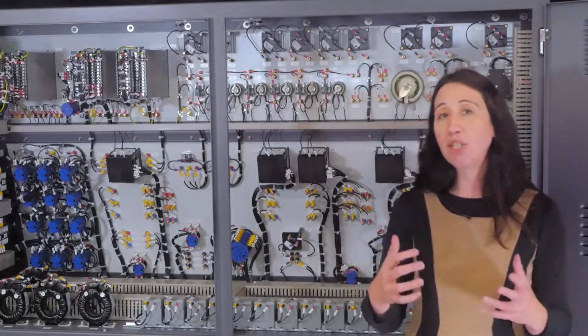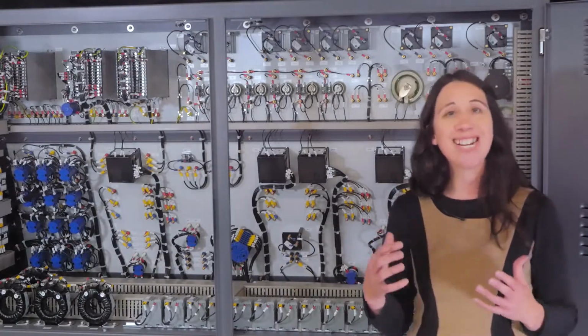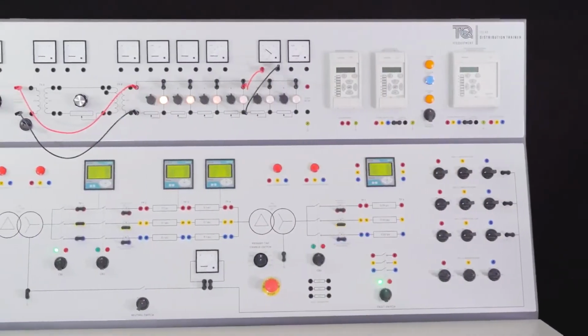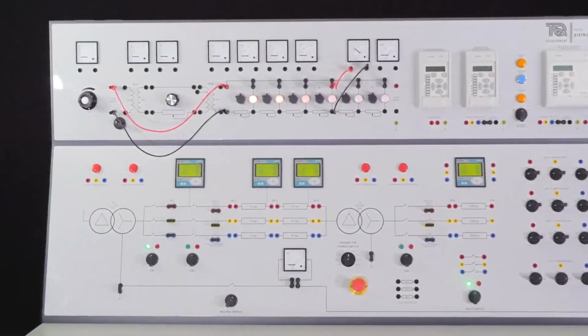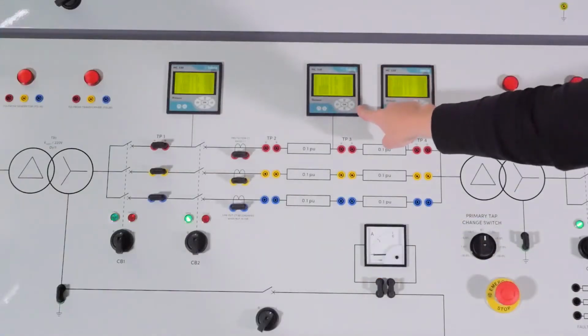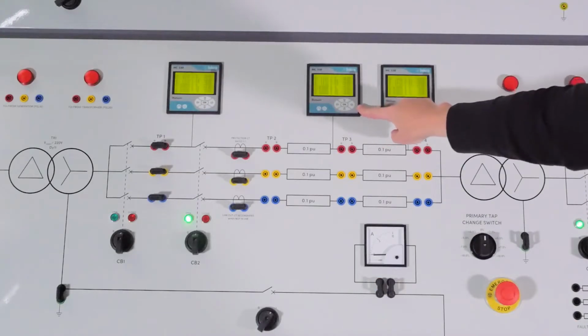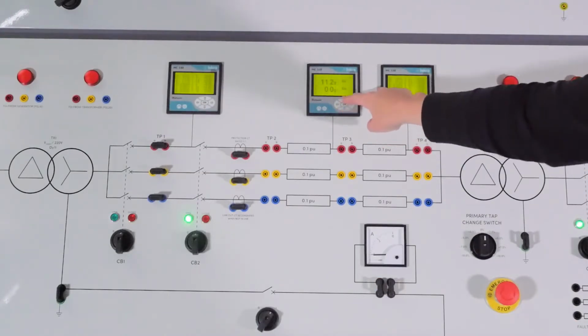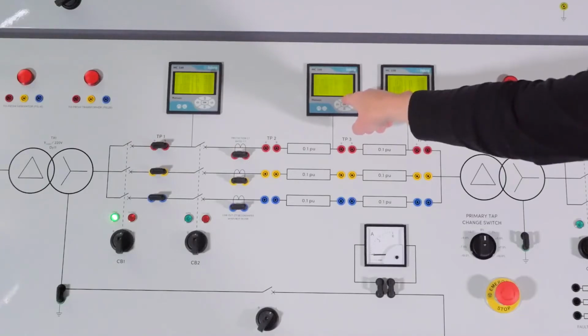The 4 digital multifunction meters are identical in their measurement capabilities. All are connected to the line by current transformers. The front panel of each meter contains a liquid crystal display and push buttons for navigating the menu. The menus allow the meter to show either a small quantity of measurements with a large display or a large number with a small display.